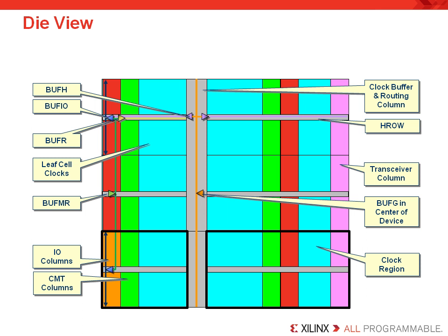Now, one of the most significant differences with the 7 series is that the CMTs, the clock management tile column, is placed next to the I/O columns. Recall in Virtex-6, they used to be placed in the center of the die. Now, this assures a minimum routing delay, which is necessary to assure optimum I/O performance for serial gigabit transceivers as well as SerDes functionality.